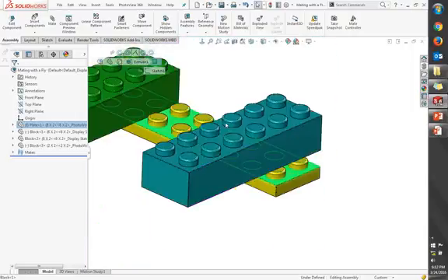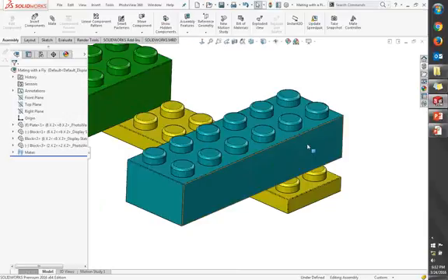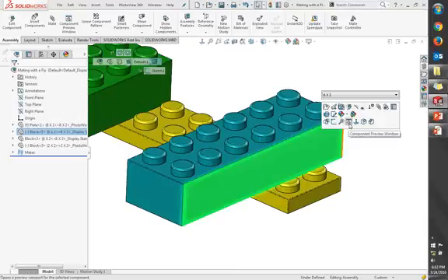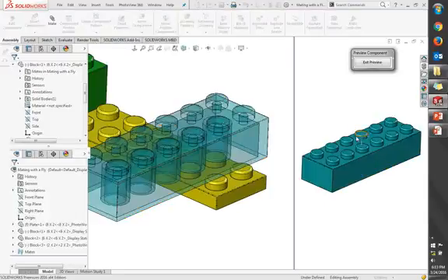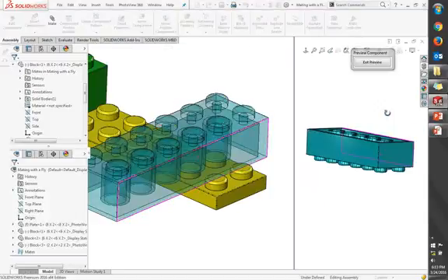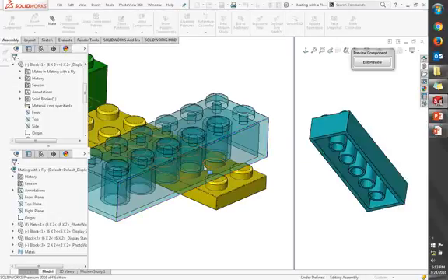So one of the new tools that we have available is the ability to pick on the part, and right here you're going to see the component preview window. This is new to 2016 as well, and at first when I saw it, I'm like, damn, that just seems kind of weird. Who would ever want to use that? Here's a perfect application of it. I pick on it. The part gets opened up side by side. I can rotate this around differently from the assembly over here, so I don't have to deal with it.